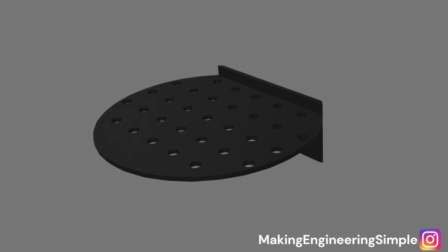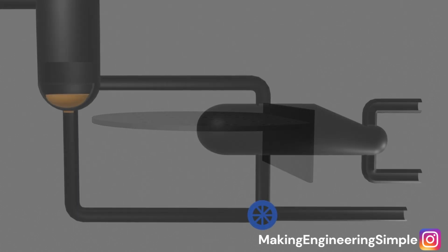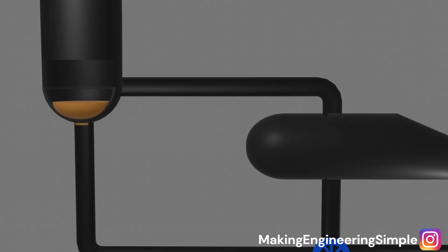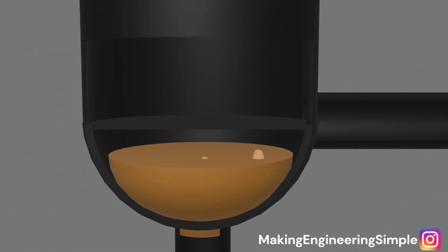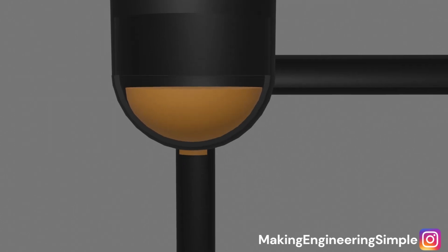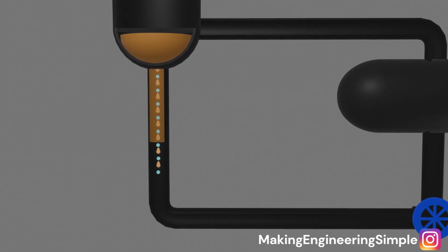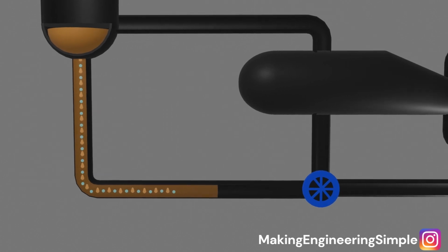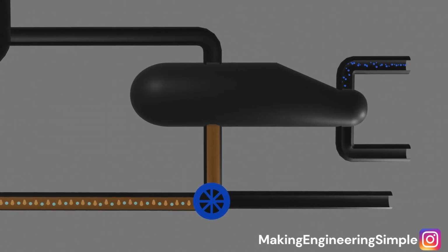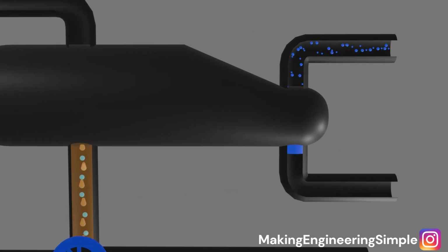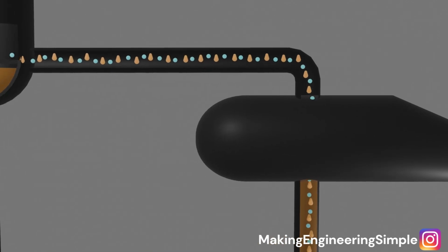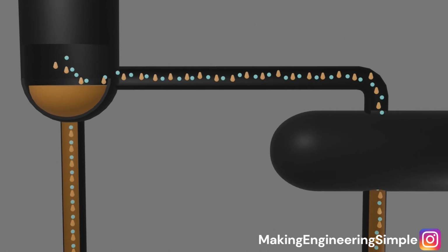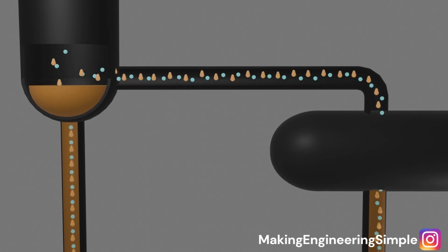Eventually, the heavy liquid completes its journey down the plates and pools at the very bottom of the column. From here, it slowly flows into the reboiler, typically a kettle-style reboiler, to be reheated. Inside the reboiler, steam is pumped through a tube bundle, transferring its heat into the liquid. This intense heat causes a portion of the fluid to boil and vaporize. This newly formed hot vapor is routed directly back into the column to maintain the upward pressure.